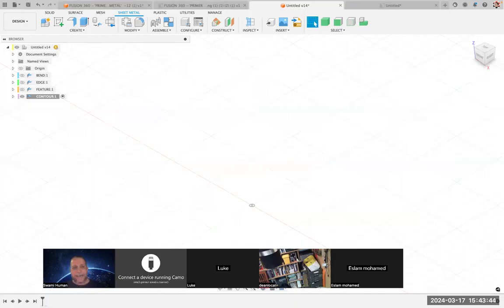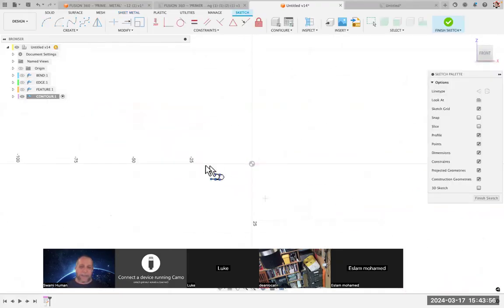And this is just a simple curve or line. So I'm going to go ahead and create a line, L for line. I'm going to choose the front face this time, the front plane, like that. And you can make any simple straight line thing. I have a sort of M looking thing, but it doesn't really matter for what we're doing here. Maybe I'll make it a little different than the other file. There we go. Hit enter.